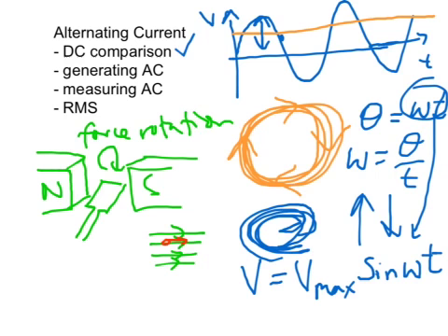It's only when, if you consider the circular path that a single piece of this wire follows, as it's going upwards and cutting the field, or downwards and cutting the field, it's going to apply a force to the charges, driving them around the circuit, and those forces are according to right-hand rules and all that kind of stuff, or different rules for a generator depending how you want to use it. How we started with this is that it'll vary between a maximum and 0, and then back to maximum according to this circular path moving through the field.